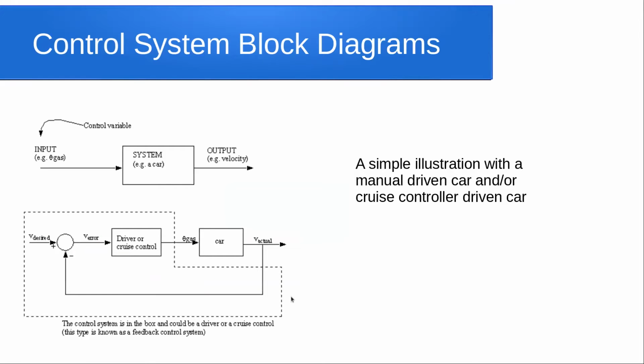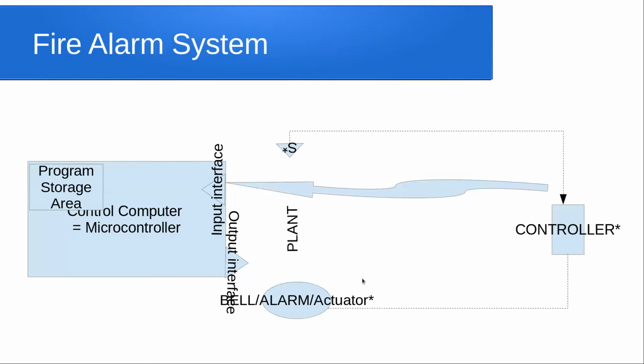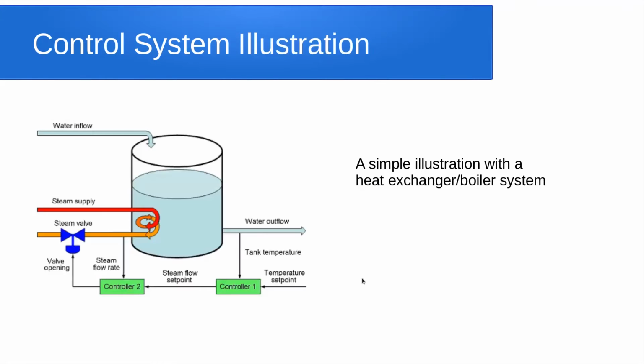So this is a simple autonomous system having a kind of cruise control. There are some sensors sensing the current actual velocity of the car, and then there is a desired set point, which both are read by the cruise control system. The output is generated, or the throttle is pressed, or the angle of the throttle is set in such a way that the difference between the desired velocity and the current velocity is minimized, or at least zero. Right, that is what is happening.